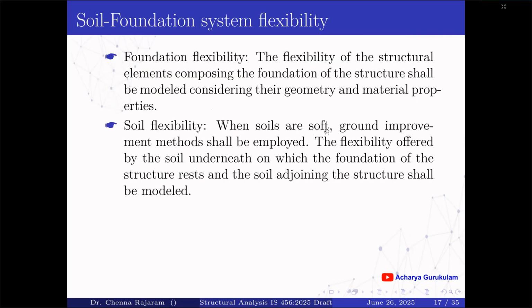For foundation flexibility, the flexibility of the structural elements composing the foundation of the structure shall be modeled considering their geometry and material properties. For soil flexibility, when soils are soft, ground improvement methods shall be employed. The flexibility offered by the soil underneath on which the foundation of the structure rests and the soil adjoining the structure shall be modeled.